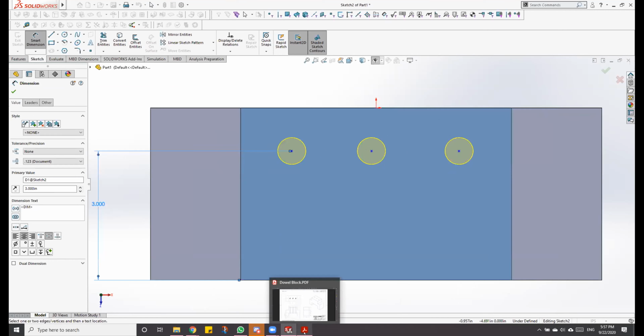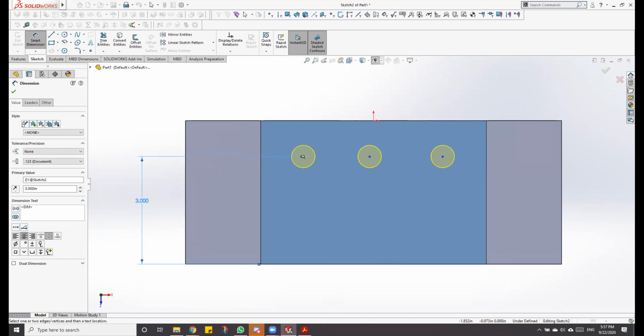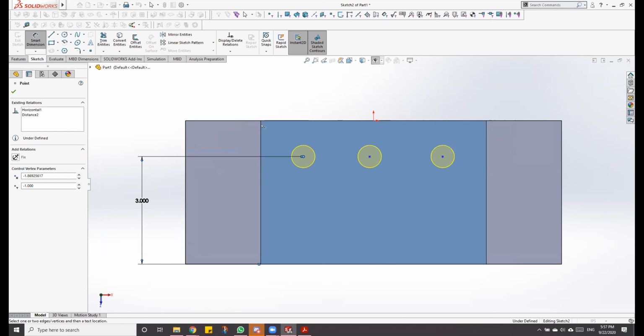Next, we have an ordinate dimension. You can actually do ordinates in a SolidWorks part. It's not common to do it within a 3D part, but I have seen people do it. If you feel comfortable doing that, you can go ahead. Otherwise, we'd have to create 3 of these different dimensions going back to the 0. In our case, I'll show you how to do the ordinates so you are familiar with them. It's the same thing when you're doing a drawing.